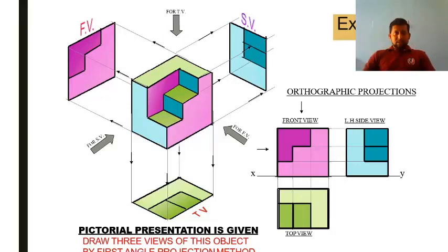This one I clearly mentioned some time back. When you are seeing this from the side view, we can see this particular L shape, so that L shape is drawn here. One more important point here is, in each view, what are the two dimensions you are able to see and which dimension is going to be zero. Zero in the sense it is there, but you cannot see that dimension in that particular view. Now I am talking about the side view.